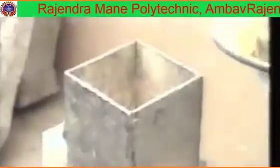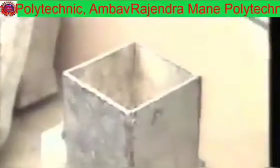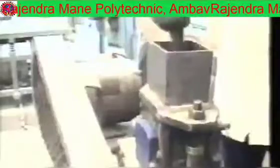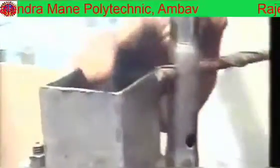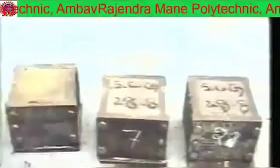Place the sample in the mold fixed on the vibration machine now. The mortar will be tamped with a rod 20 times. Mix is placed again in the mold and tamped again 20 times. Vibrate the vibration machine for 3 minutes. Remove the mold with the base plate and smoothen the surface with a trowel. Keep it at room temperature for 24 hours. Then remove it from the mold. Keep it in water curing for 27 days.